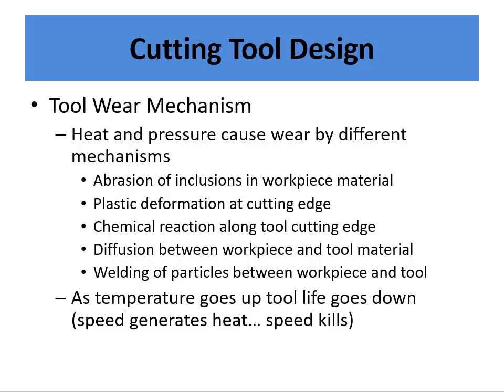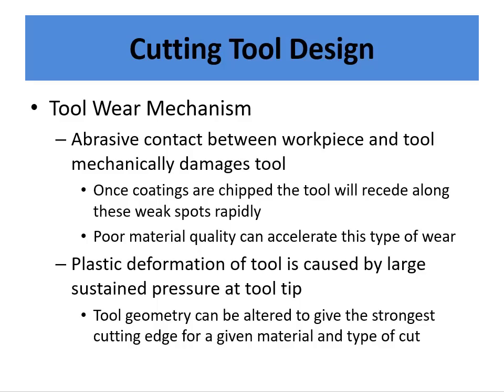You can have things like vibration that could wear the tool out as well, but you might call that a form of pressure, effectively, is how it would manifest. So abrasive contact, which is more of a pressure problem, is where it actually mechanically damages the tool. So the coatings that are on most tools are layered in such a way to provide heat resistance, and they also provide some sort of wear resistance. But eventually they'll break, and once they start to break down, then the tool will start to break down really quickly. Okay, and most of the time that happens abrasively.